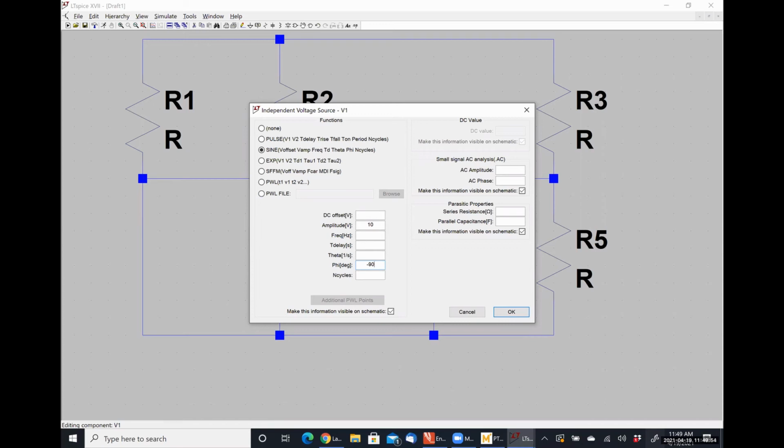But it's legitimately easier to just put your answer as a sine in LTspice, and it'll be a direct apples to apples comparison. But if you put the cosine function in, everything is going to be shifted, and it's going to look like your phases are 90 degrees out of phase for everything.